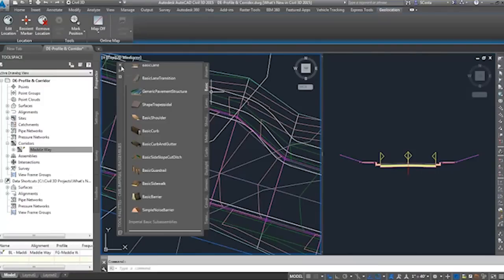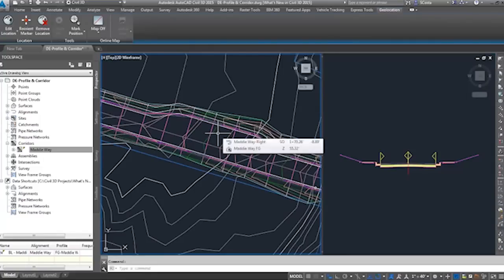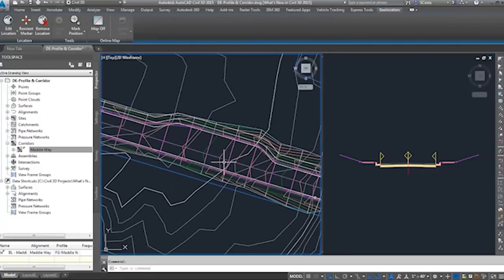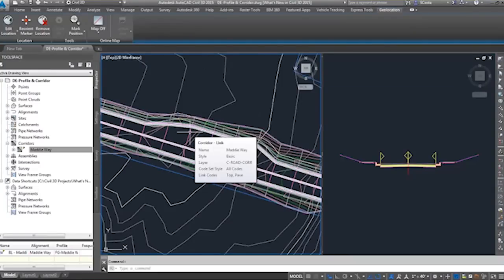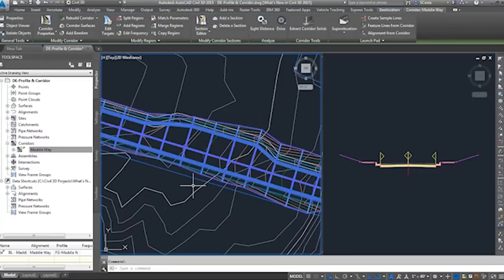We'll talk about the second aspect of Civil 3D corridors that's kind of new and exciting. Now, in previous versions, of course, you're all familiar with frequency and how that applies to corridors. So I'm going to pick my corridor, and you'll see that through my contextual ribbon, I can change the frequency. And the frequency, for those of you who are new to Civil 3D, only implies that for any given corridor, how often is this assembly dropped in to create my Civil 3D model.